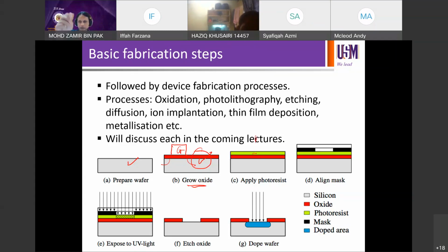You dispense a few ml depending on the technology, and then we spin to cover the whole surface, and then the surface will be covered with a light sensitive polymer compound, right? Which will act upon exposure to the illumination light later on in the scanner. Okay, and then you're going to use your mask. So this black and white is actually your mask, which will allow the light to pass through certain areas.